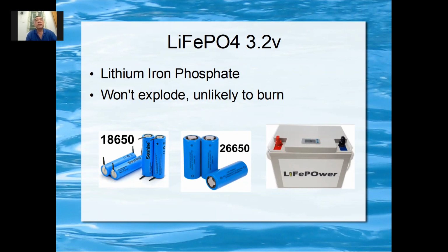So what to do if you want, let's say 48 volt, then you must buy a battery pack that is already 48 volt. One battery pack that's 48 volt, because built-in there is a battery balancer that will balance out all the charges for the batteries internally to get 48 volt. If you want 24 volt, you must get one battery pack that is exactly 24 volt. Don't get 2 12 volt and connect them. It's not advisable. Not to say it won't work. It's not advisable.